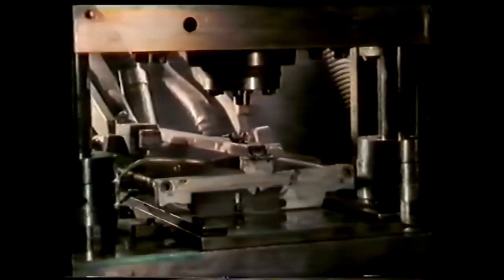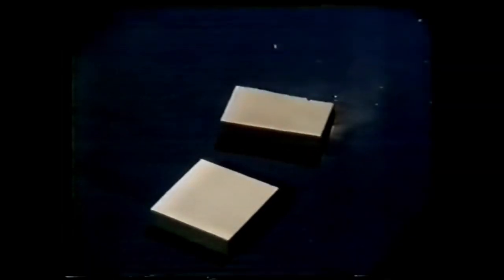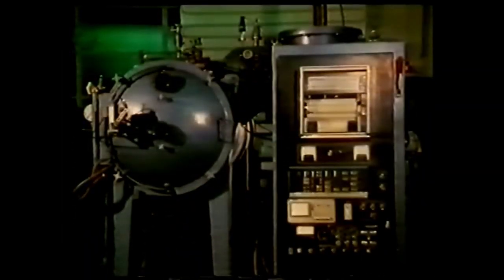These are produced by a method known as powder metallurgy. Carefully measured powdered high-speed steel is put in a press. A die then compresses it into the desired shape. At this stage, the insert is known as a biscuit, and it's very brittle or friable. The inserts are baked in an oven at a very high temperature in a carefully controlled atmosphere. This causes the particles of high-speed steel to shrink and bond together, making the insert extremely hard.